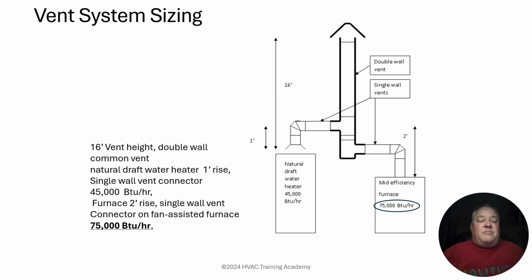So when we look at that point, that's where we would look and see, okay, we've got a 4-inch vent connector on the water heater, we got a 4-inch vent connector on the furnace, and then we had a 5-inch common vent. Usually the common vent, in fact, it's extremely rare that the common vent is going to be smaller than either one of the two branches. It's always going to be at least one of the sizes, the smaller branch anyway, usually the larger branch, or a step up again in size. In this scenario, I'm talking just about what I just did in the last one.